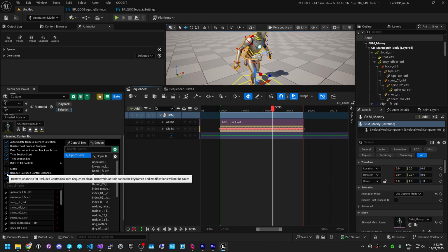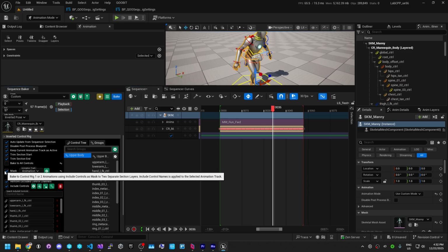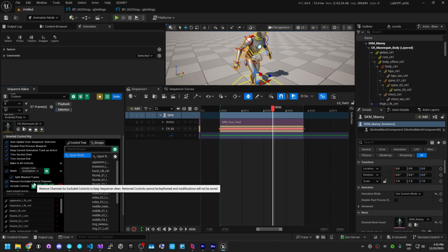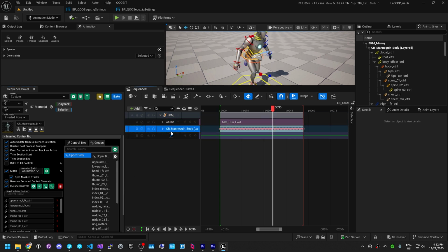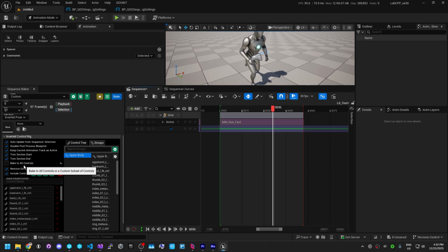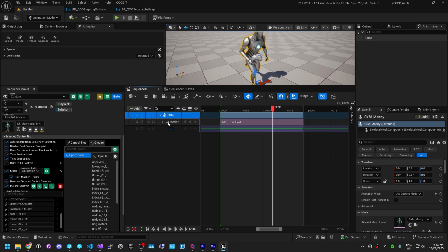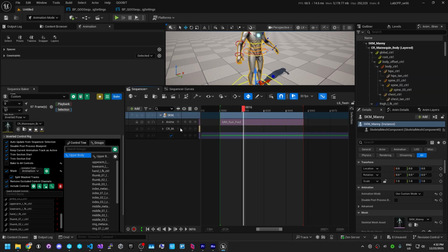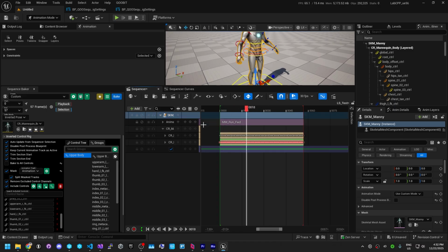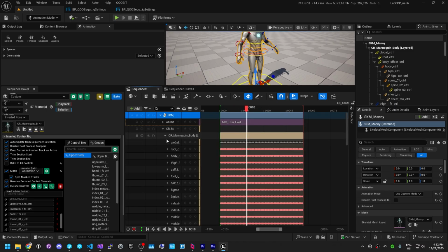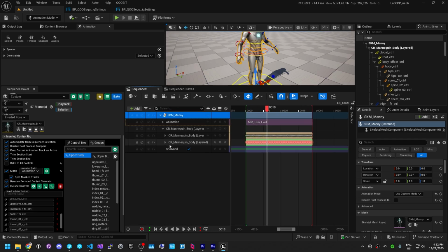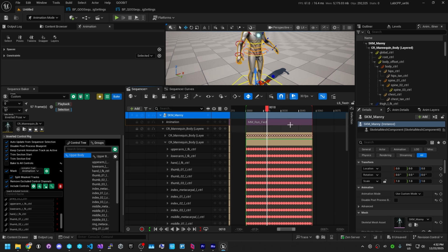All right, so similarly to the other sections, we're going to show how to mask. So when we are masking, generally we want to keep this as well. We're going to show another case with it off as well for completeness. But we're going to use one animation clip, and we're going to do a split bake that is happening to mask, and we're going to be masking out the upper body into one layer and the rest into a separate layer. So coming out of here, we still see that it is still in bind pose, but we have two separate sets of controls, one for the lower body, bring this out here, and one for the upper body that is included in our control set here.